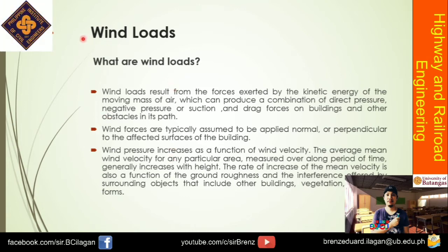Okay, so let's define what are wind loads. Wind load results from the forces exerted by the kinetic energy of the moving mass of air, which can produce a combination of direct pressure, negative pressure or suction, and drag forces on buildings and other obstacles in its path. Wind forces are typically assumed to be applied normal or perpendicular to the affected surfaces of the building.